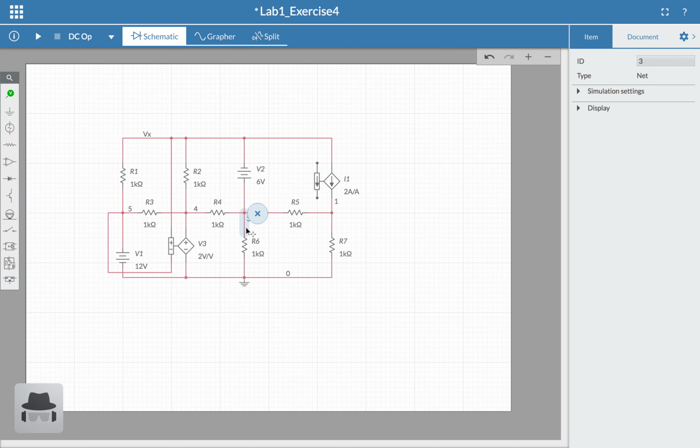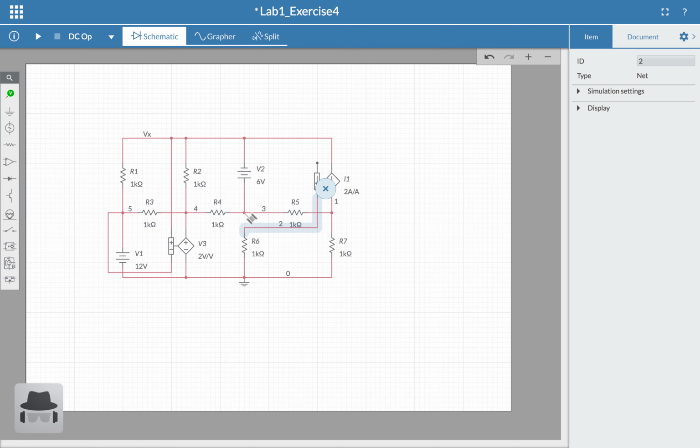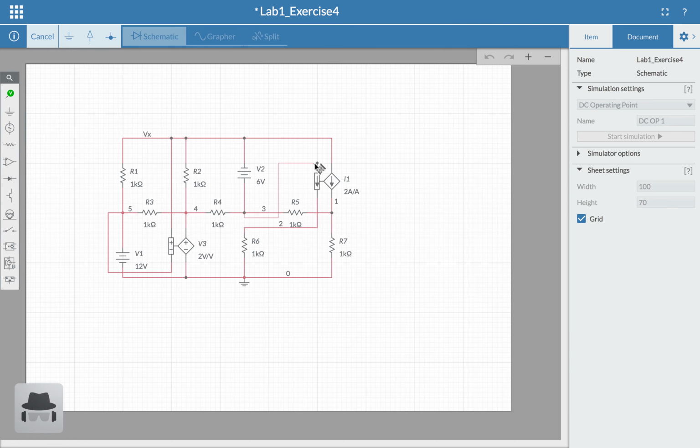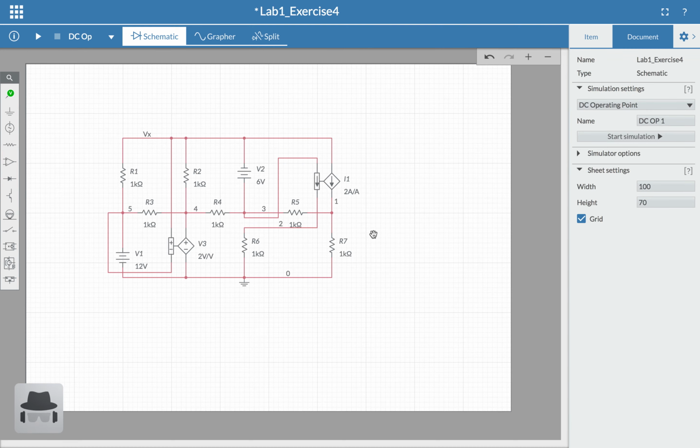So we're going to break the circuit right here, and then we're going to take this guy and run it in here. We're going to take that guy and run it in there. So now you can see the current's going to go in here through our little measurement device, which is going to tell this guy how much current to generate, and then it's going to go back through in here. So I hope that's clear to everybody. And you can see where these are crossed. There's no dot there, so it means they're not connected there. If they were connected there in this case, it would be bad. But sometimes you'll see wires like this, and they'll cross over each other, but they wouldn't be connected in the center, and so that's a problem as well.